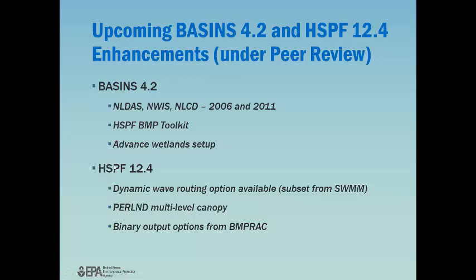Now within 4.2 will be a version of HSPF referred to as version 12.4. This has a dynamic wave routing capability, a subset of the EXTRAN capabilities within SWMM. It now has a multi-level canopy compartment within PERLND. Previously, everything above the land surface was considered vegetation with one set of interception and land cover characteristics. In order to